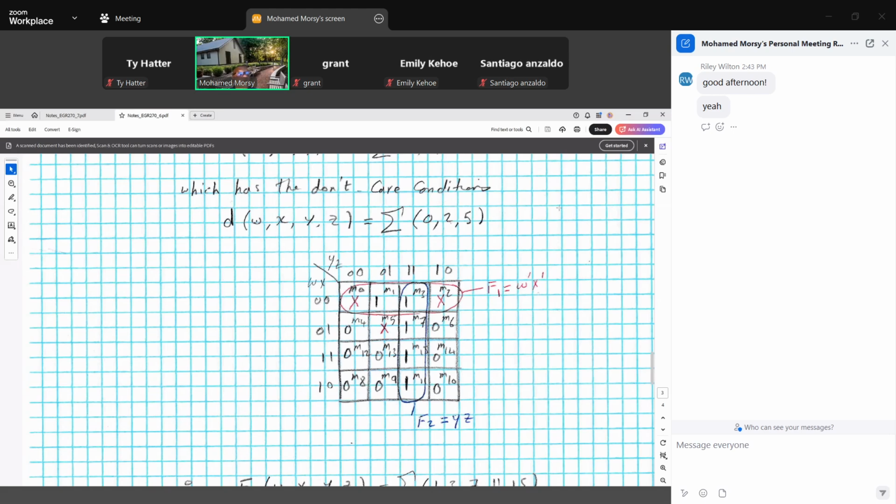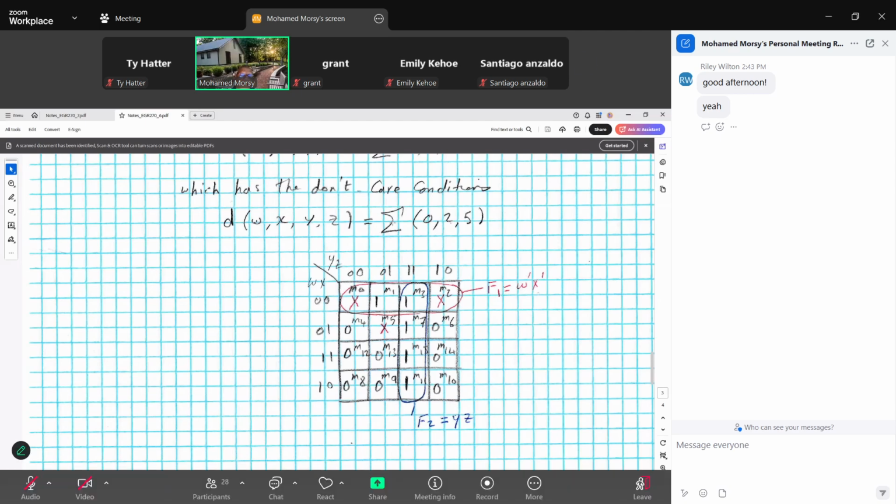So when we have don't care minterms, this allows us to get more adjacent ones in one group. We start with 8: after we fill out the Karnaugh map, we look at 8 adjacent ones first to take in one group. If not, we look at 4, then 2, and so on.